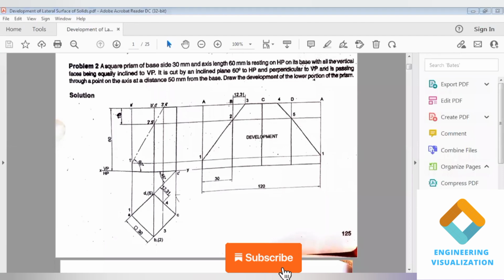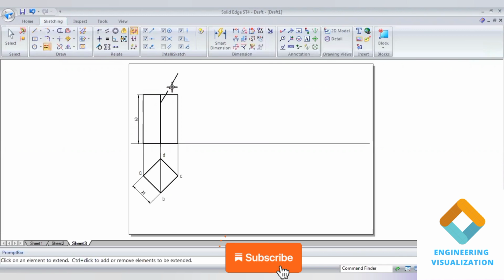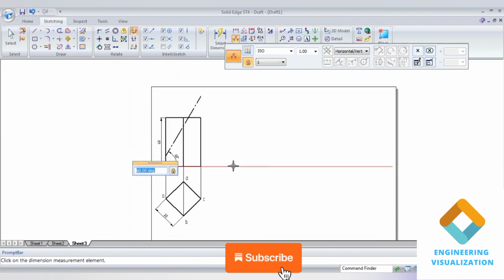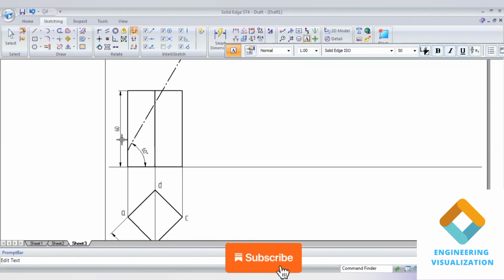So I have drawn one line for reference, and then I am drawing a section plane. Taking this as the axis plane, now giving the angle of 60 degrees. That angle of inclination will be 60 degrees here, so type 60 and enter. After this go to next and extend this line. This is where it is cut. Now we can show the angle for this section plane. The angle of inclination is 60 degrees.